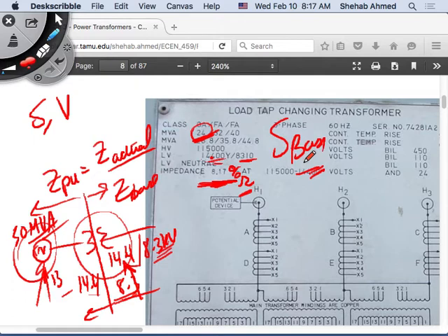It's almost like, okay, I will go back to calculating actual values. It makes sense. You can go back and calculate actual values, right, if you have all the bases? If you have the base value for impedance, and you have the per unit value for impedance, can you go back and calculate actual values? Yes, you can. So it's like having to go back and calculate actual values and then calculate the per unit values on a new base.